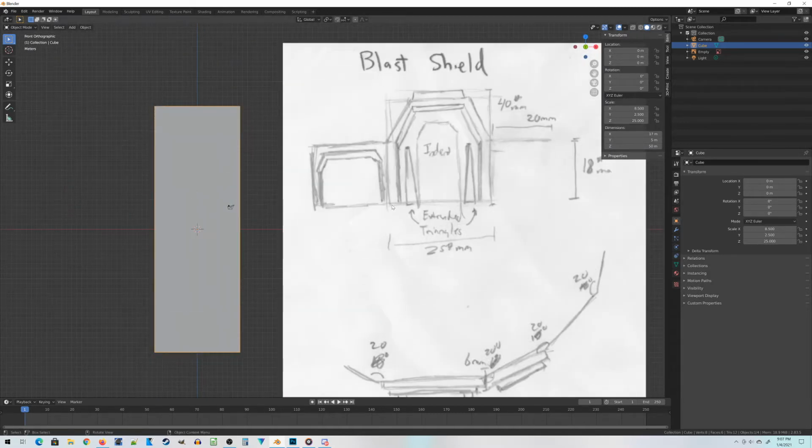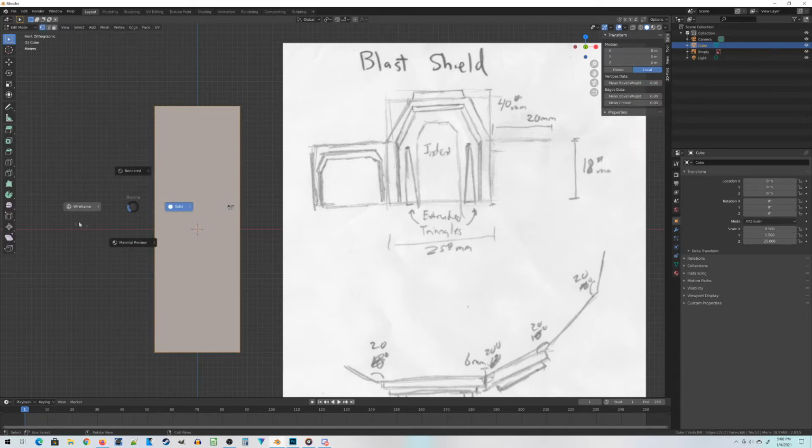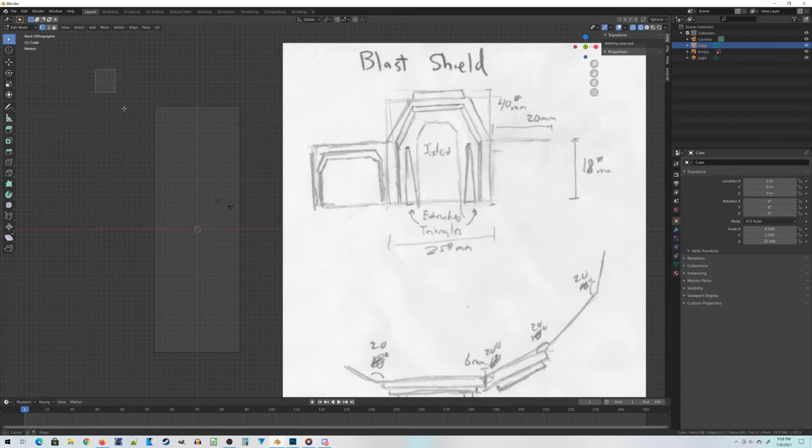Now this shape here is pretty much, you want to add an extra vertex and then just indent the top one by a certain distance. Pretty simple, right? So let's jump to edit mode, press Tab. Let's go into wireframe mode. I'm going to box select, letter B.